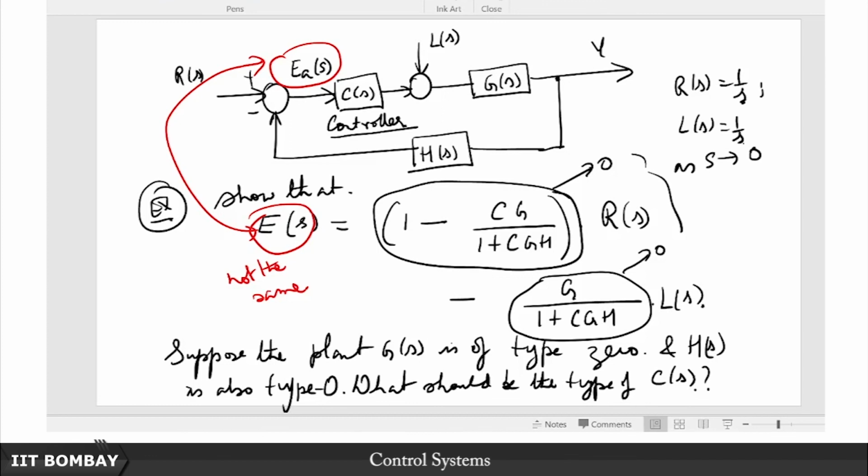Alright, so we said that now we are concerned with a polynomial being Hurwitz or not. For that we even exclude that imaginary axis. Okay, so we will come up with this strategy to find out that given a polynomial, whether all of its roots are in the left half plane or whether there is even one fellow that is on the right half plane. Remember, for stability you need everyone to be on the left half plane. For instability, even one of those poles being on the right half plane suffices to spoil your party.